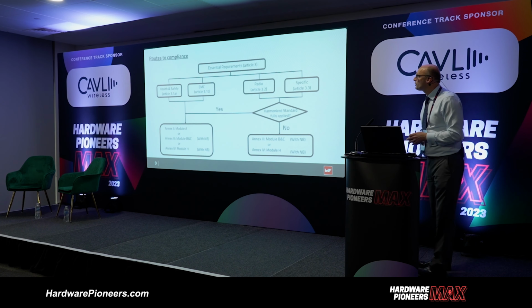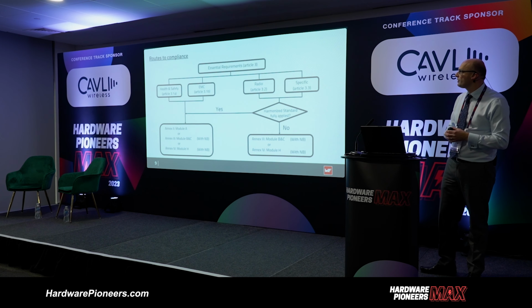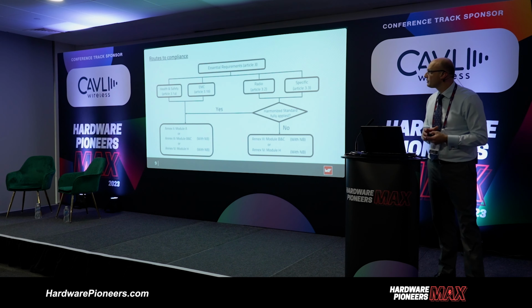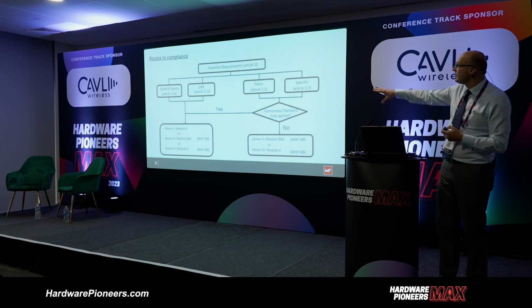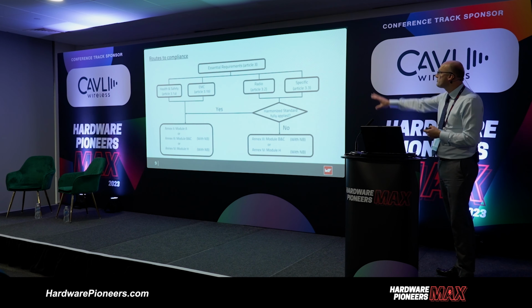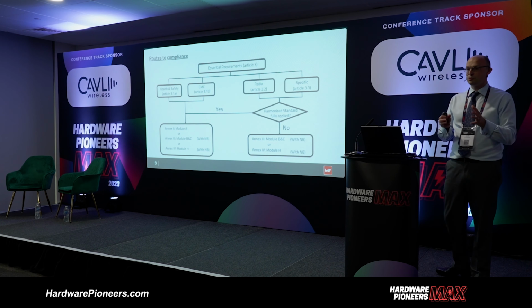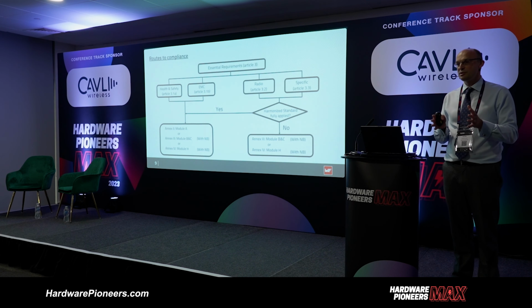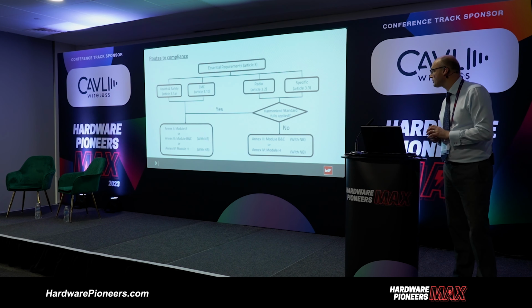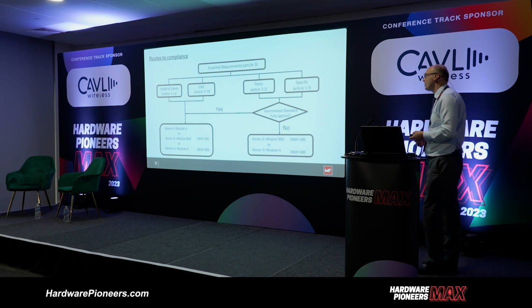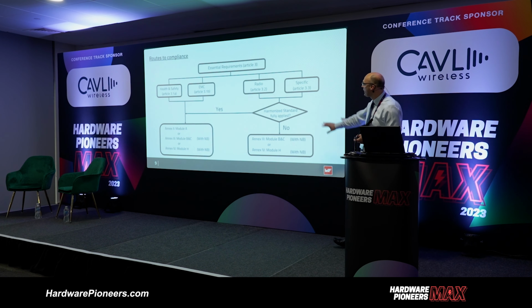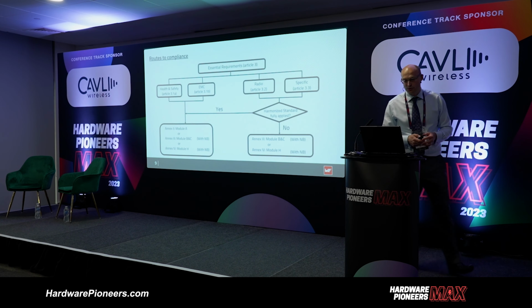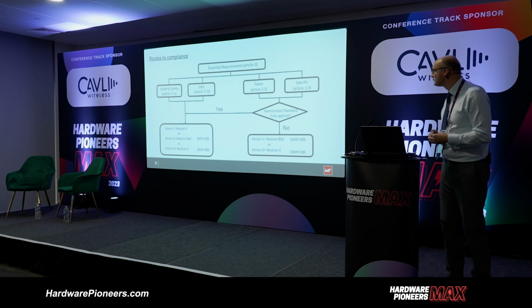So here we just have a very quick overview of the routes to compliance. I've mentioned before Article 3.1a health and safety, Article 3.1b EMC. These we can self-declare. Article 3.2 is the real critical one because that's ensuring you have effective use of the RF spectrum. So if you use your harmonized standard in full, then you can self-declare. If not, then this is where you will typically use what we call a notified body.